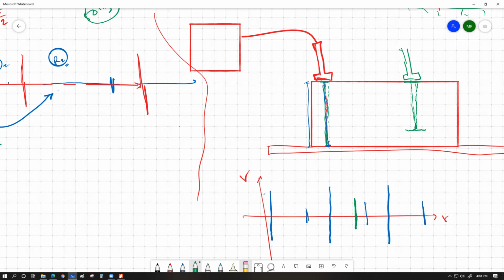For example, if this whole thickness is, let's say, 10 centimeters, that would mean that each of these original reflections had to go through a total of 20 centimeters of metal medium, and they underwent a certain amount of reduction. Whereas if this crack is, let's say, 2 centimeters above this surface, which would mean it is 8 centimeters below the top surface, these green waves actually had to travel 16 centimeters, which is a bit smaller compared to the original full reflections of 20 centimeters, which means they will have a little bit less reduction.